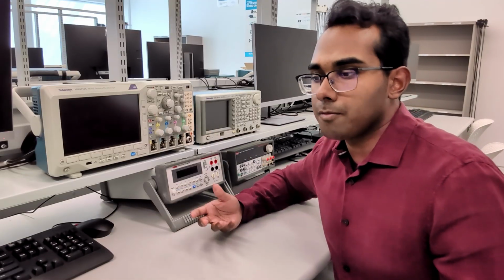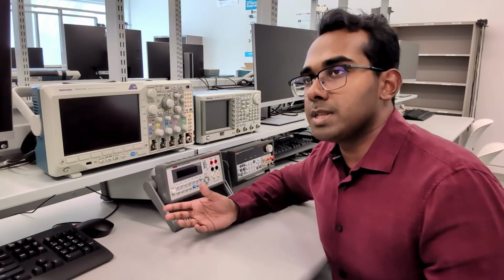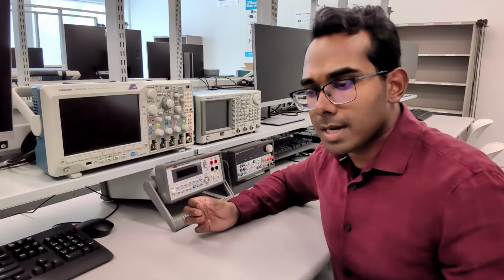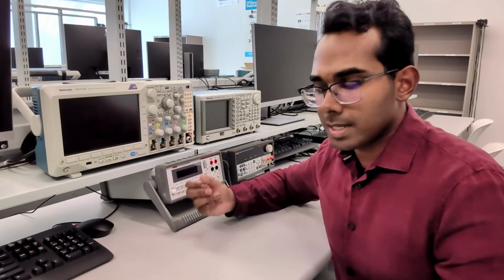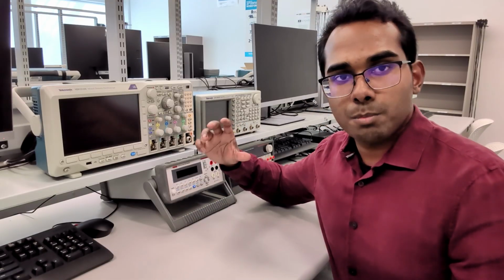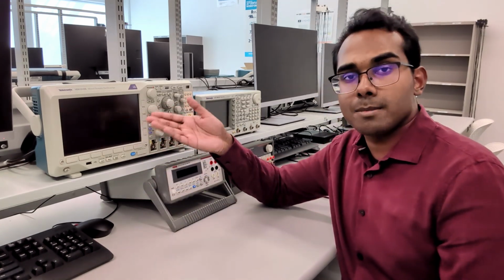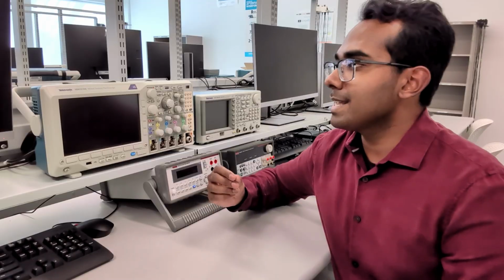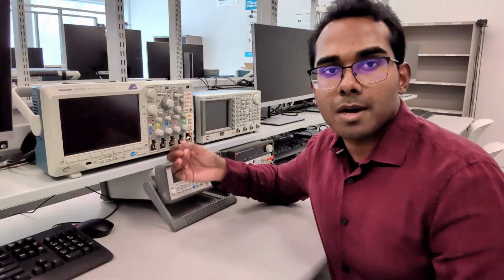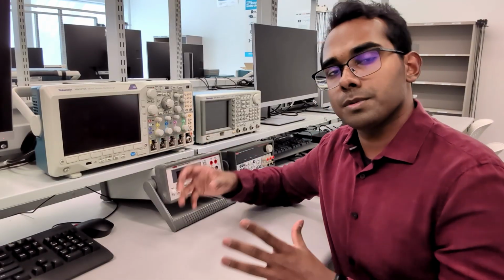And that's really useful for us whenever we're, say, building an RC circuit, a resistor and capacitor network circuit, where it creates a voltage pulse whenever we send a DC voltage through it. And we can see exactly what that pulse looks like at different moments in time using the oscilloscope. So now let's get into how we can actually set this up to read and plot those voltages at different places in our circuit.